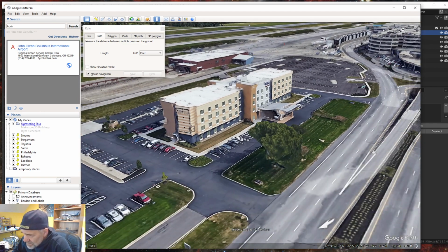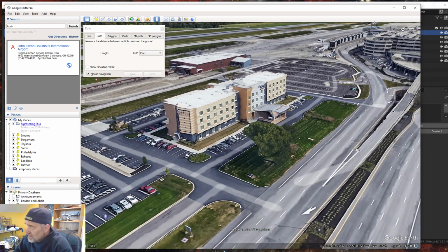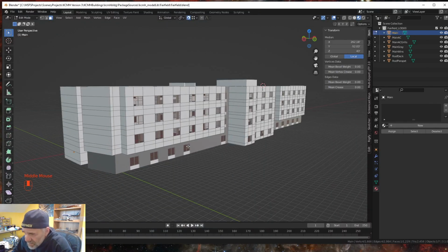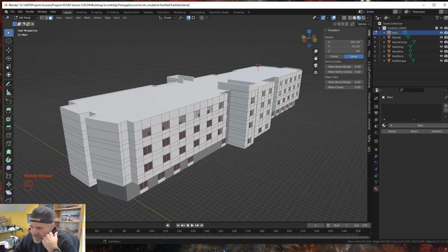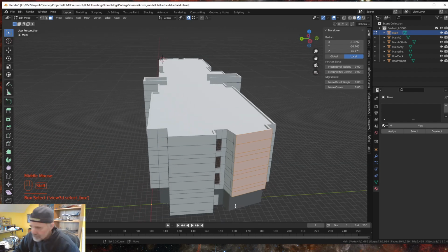I know I disappointed all of you. Alright, so we're just gonna make it appear. So we need 2 more stripes in between the windows, right? So, I don't want to put a loop cut on the entire building. So what I'm going to do is I'm going to select these end pieces like this.